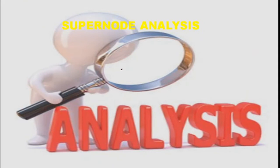First, let me clear what is node analysis. Node analysis is a technique which is used to find voltage across various elements of a circuit. Node analysis is preferred when the circuit is excited by current source and the voltage across various elements is unknown.